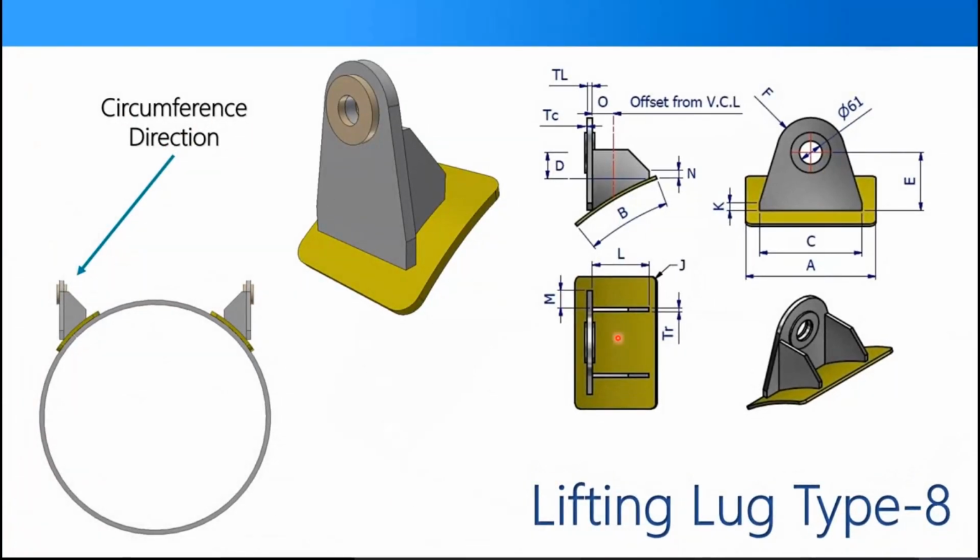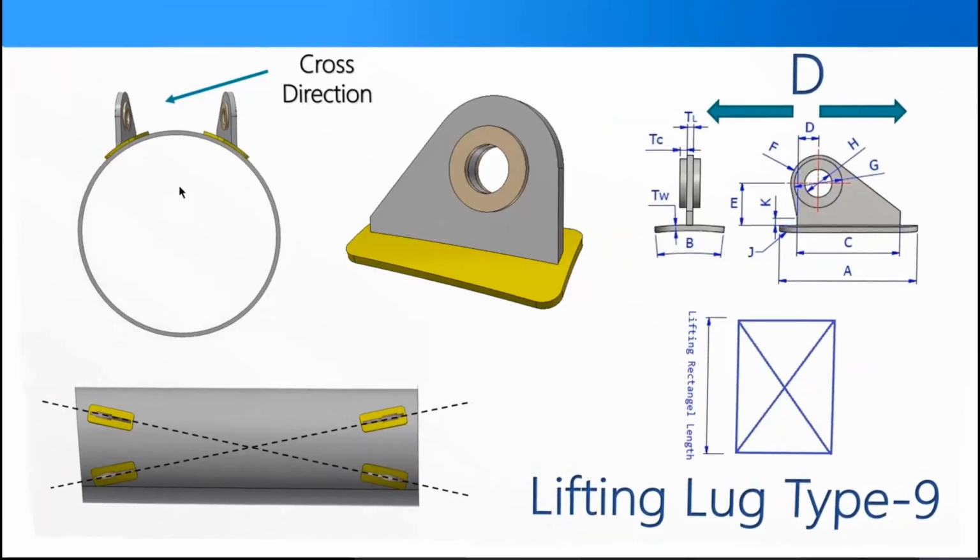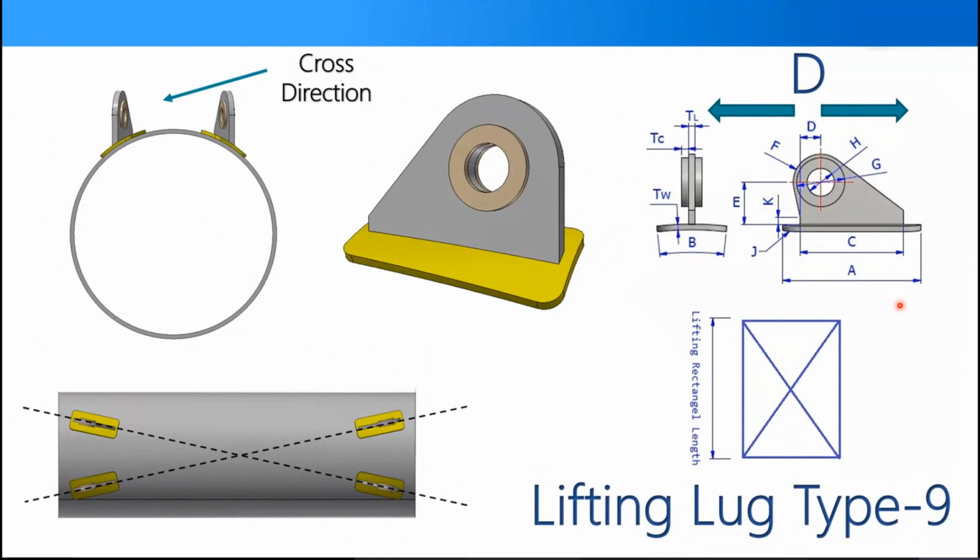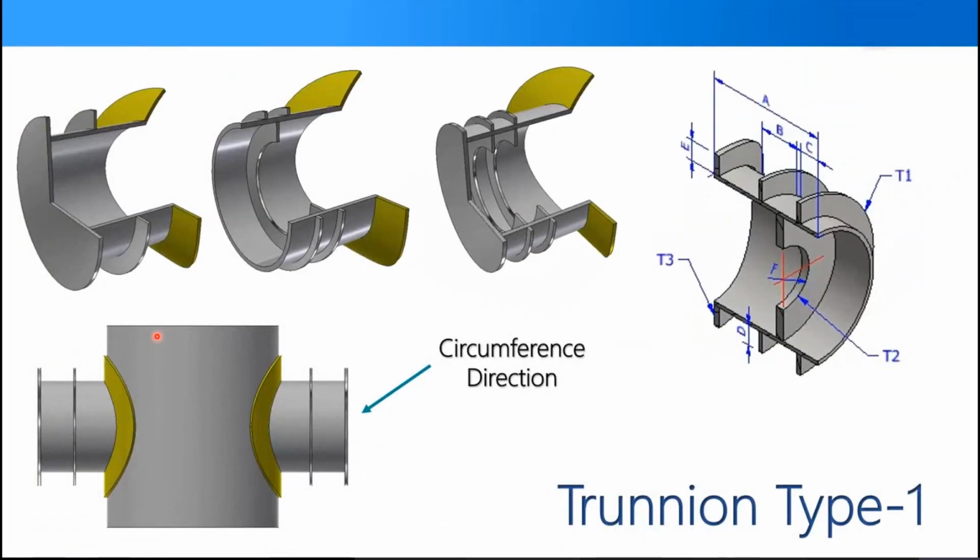The trunnion type: you can see that you have the ability to add an end blade, and all of that is optional. In this case, it doesn't exist. You have the ability to add an inside ring, so you can see that we have an inside ring. In this case, it doesn't exist. This ring, you can make 2 rings inside instead of 1, so you can add 1 or 2 or none. The same for the external ring: you have the ability to add an external ring or 2 external rings. So there are many different options you can make on the trunnion.